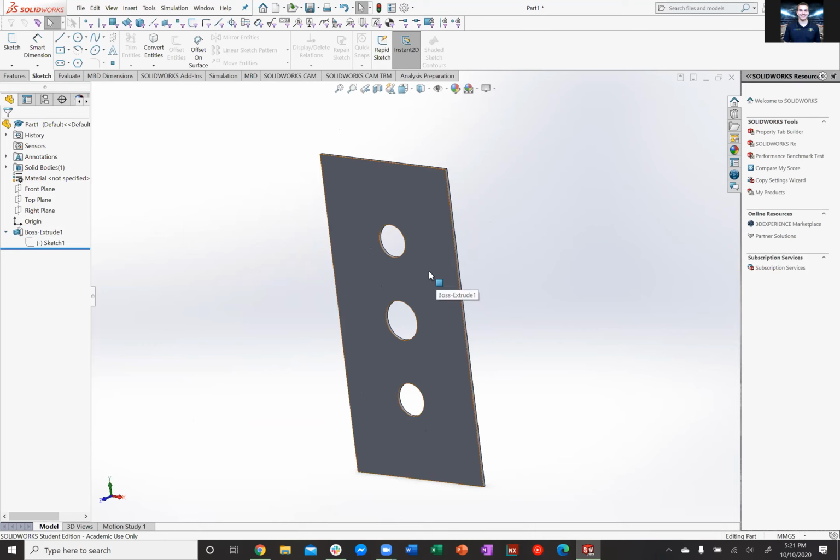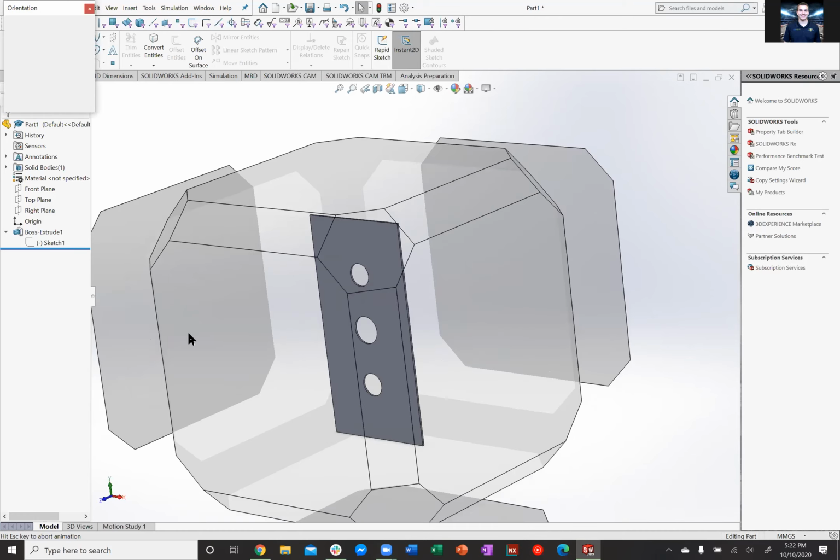So when you're designing sheet metal, consider the different thicknesses that are available, either if we're going to buy it ourselves from McMaster or from a company like Mass Precision. We have specific thicknesses, and if your thickness is not one of them, then it might be more expensive because we need to order that on a special order.